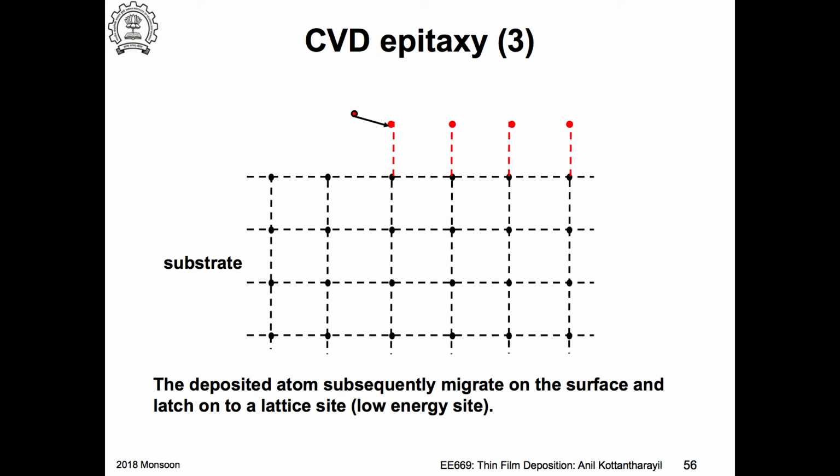controlled region. That is why we had seen certain atmospheric pressure reactors, where the designs were such that you have a wafer placed on a susceptor which is slanted. You have a constriction, so the cross section area through which the gas flows reduces as the gas proceeds.